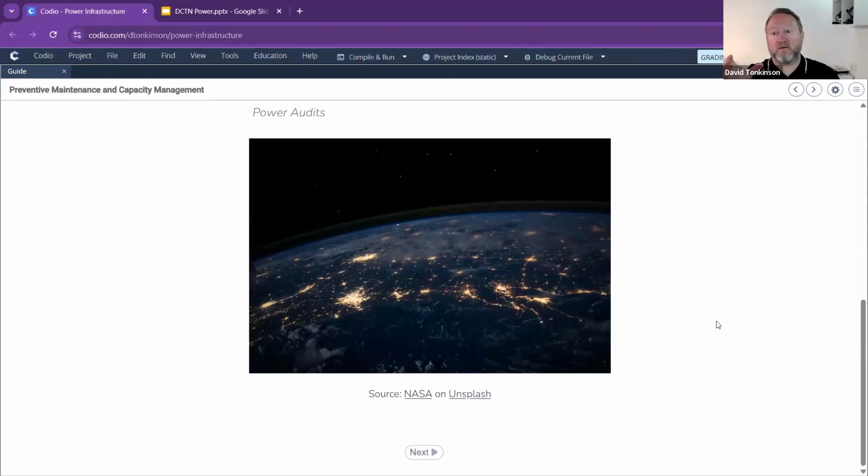Okay, when we talk some hotspots, there's two ways to look at a hotspot. You can use infrared, which basically allows you to see the cables that are getting warm. That means they're drawing more power. The more power that goes down a cable, the hotter it gets, and therefore we can pick it out like that. There's also a whole load of electrical monitoring tools that are basically put on. You can either clamp them around cables, or you can have a PDU that's basically got some monitoring systems on them.